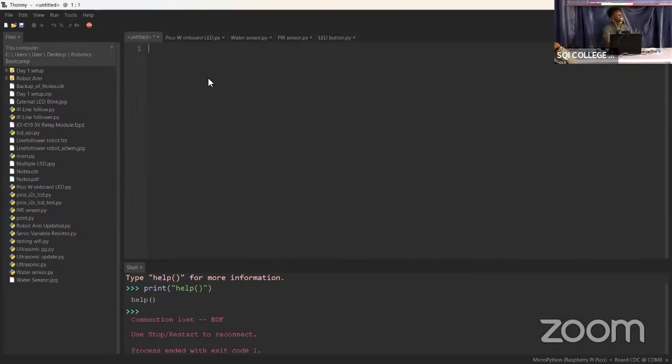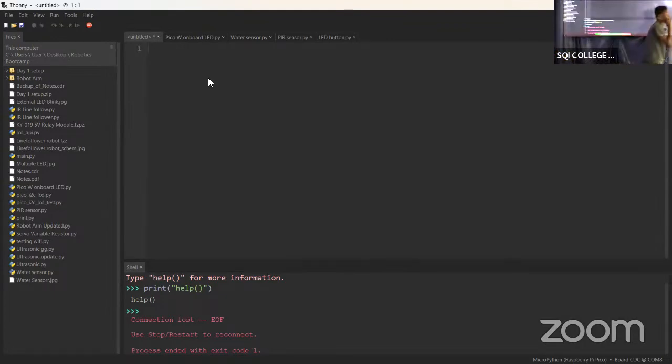Now to run controllers with Python, there is a default library in Python called machine. From that machine library, we are picking a function called Pin. Pin signifies every port you have on that controller, and every pin number that was assigned to every pin on that controller. So I'll be calling that library and importing Pin.